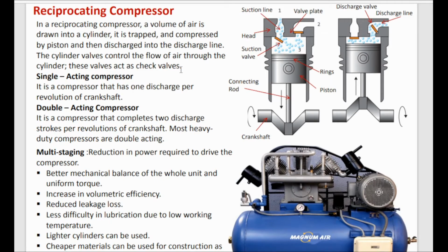Here, let us see how this reciprocating compressor works. So here this crankshaft is rotated by the motor, and when this piston moves downwards, the pressure here will go down, and that will be lesser than the atmospheric pressure.